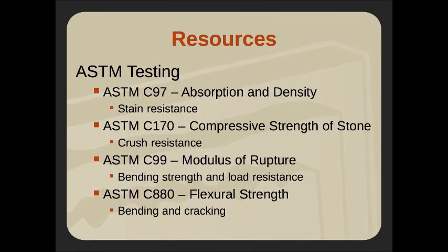Compressive strength, C170. This is important if I'm stacking a wall as opposed to using mechanical anchors. How much compressive strength does the material actually have? Can I load it, and to what extent can I load each course moving up? That bottom course has got to withstand the weight from the very tip top. So it's important. It's also critical if I'm going to use stone as an exterior paving product.